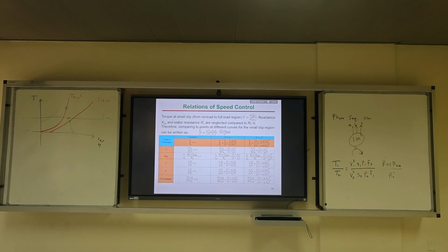It means the intersection between your motor torque speed characteristics and your actual load is your point of operation. It means under this load, the motor will behave that way. Under this load, the motor will cross at 2 different points, either high speed or low speed. Yeah, this is the intersection. So we have another intersection here.